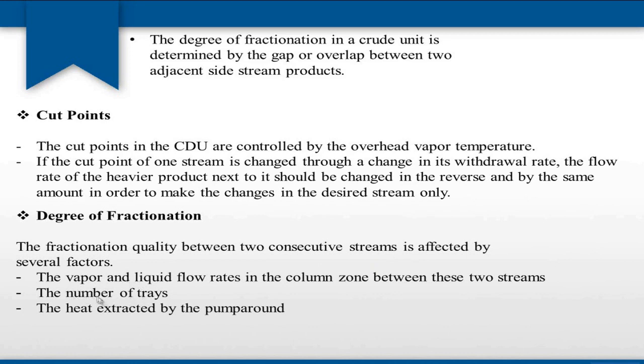And also, if we have many trays in the column, it means we will have more equilibrium phases taking place, which means a higher fractionation degree. And also we have to extract some heat out by the pump around as much as we can, otherwise the salt may accumulate at the top of the column.